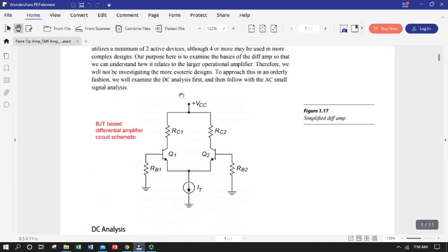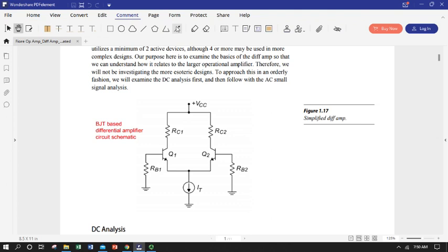Okay, so what does a differential amplifier look like? Well, here is a typical schematic, and the real heart of this is the mirror image that you can see. We have a base resistor and basically one amplifier circuit here, a collector resistor, transistor. This is shown with BJTs. We could make the same thing with field effect transistors.